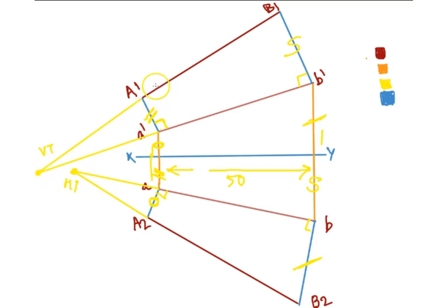For example, here if you extend this true length and the front view you get the vertical trace, and similarly this true length and the top view you get the horizontal trace. Traces are very easy to draw using the plane rotation method. Obviously you have a technique to do this in the line rotation method as well, which we will see later on with an example.